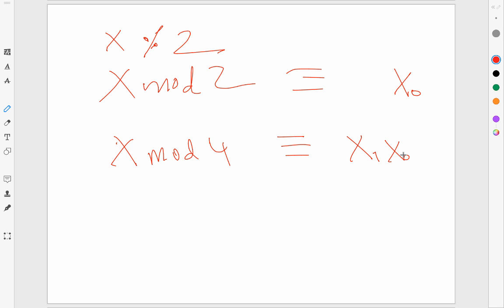Even without working through the circuit, you can do a back of the envelope calculation as to what the count is going to look like. I had a typo in the formula, so make sure that you work around that. Then one design stands out. One of the observations you'll probably see is that the 3 to 8 decoder is really, really expensive, so that's probably going to affect the choice. So that's pretty much the way to approach that question. And yes, you have to count the cost of a NOT gate for sure.